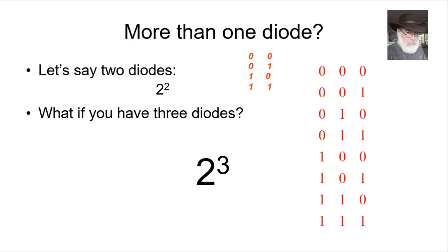What of an exam? In an exam, I would give you the circuit with the three diodes, for instance, and tell you, prove whether the connection 101 is true or false. There. And you just draw the equivalent circuit. The first diode is a short, the second is an open circuit, the third one is a short. You solve voltages and currents and you check to see if it is true that this diode is open and that one is closed. And you report that, yeah, the configuration is true because, and you explain that, or it's false because. That is for the exam.